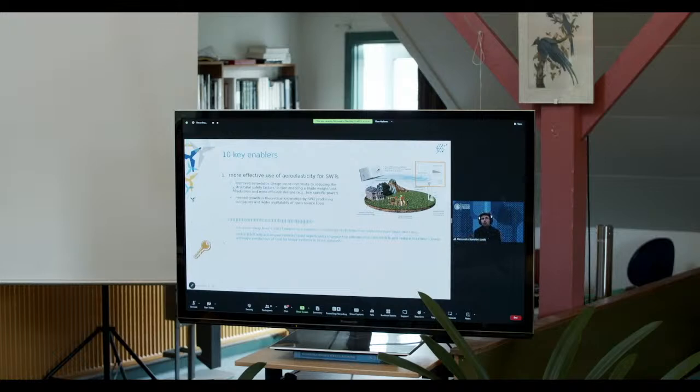We need to improve in control strategies. So we are seeing a fast transition away from furling towards more advanced control stall strategies. There are also some examples showing that individual pitch control, even though it is difficult to include in small wind due mainly to space in the nacelle and cost, could provide a real improvement in production and also an alleviation of the loads, which again could be potentially very useful to make blades that are lighter and also cheaper.